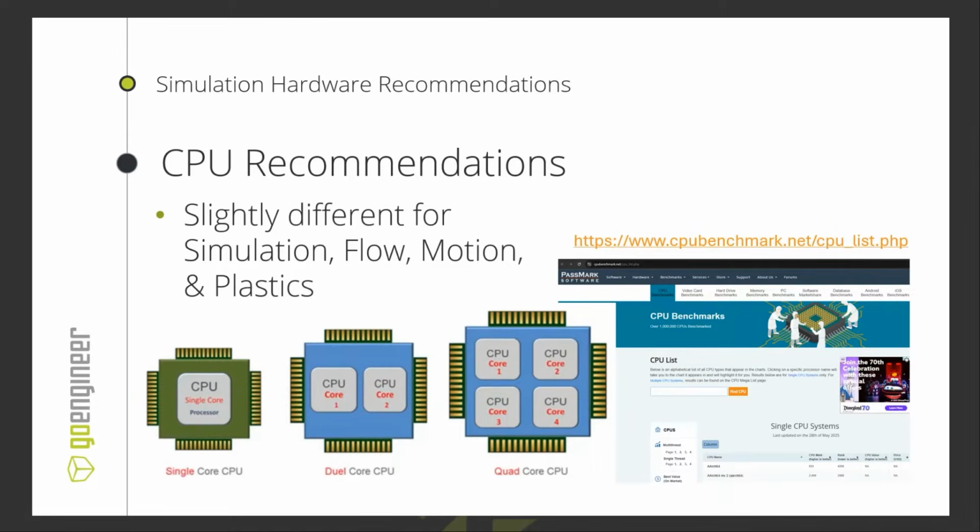Okay. So as Enrique started saying, not only are your needs slightly different, the requirements for SolidWorks Simulation or FEA are different than flow, different than motion, different than plastics. And that link there, the benchmark, is one thing you can reference. If you're looking at synthetic benchmarks, that gives you a relative indication of CPU performance. It does not exactly tell you how well SolidWorks or SolidWorks Simulation is going to run, but it gives you a general idea of how to compare or tier one processor versus another. So that might be a nice thing to start with.